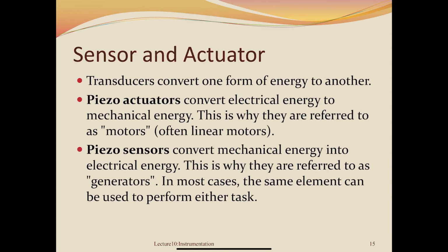So using the direct effect and converse effect, we can design or use the piezoelectric crystal as a piezoactuator or piezo sensor. So piezoactuator actually converts electrical energy into mechanical energy. This uses the converse effect. As for the piezo sensor, it will convert mechanical energy into electrical energy, such that we apply force onto the crystal, then we measure the voltage.